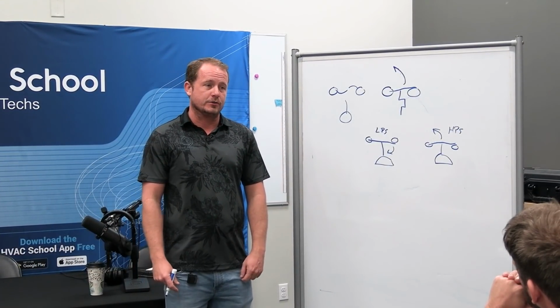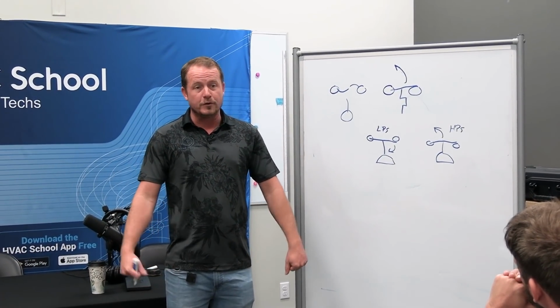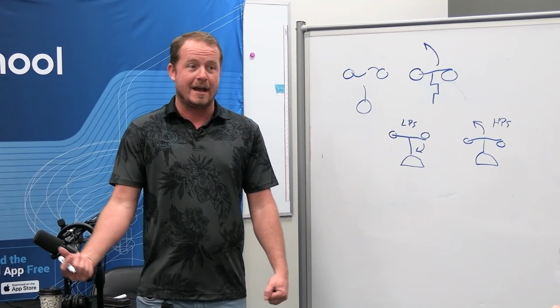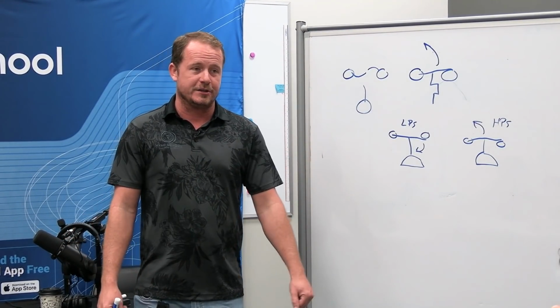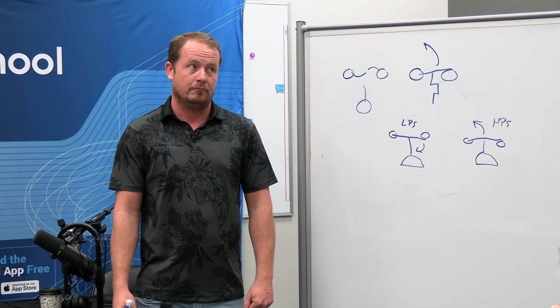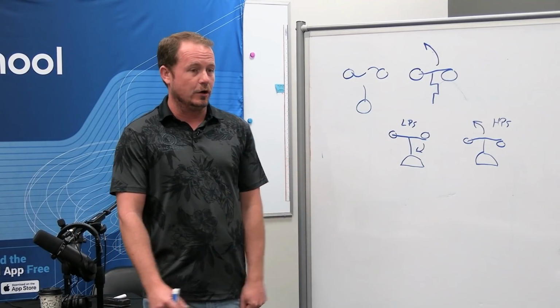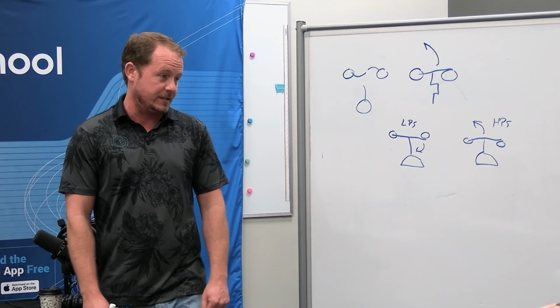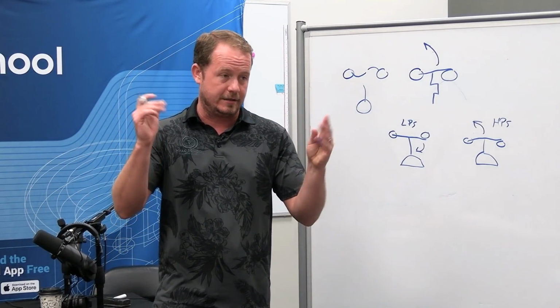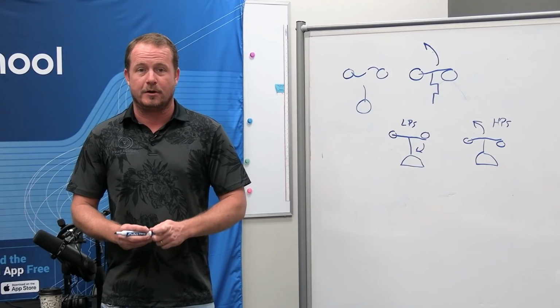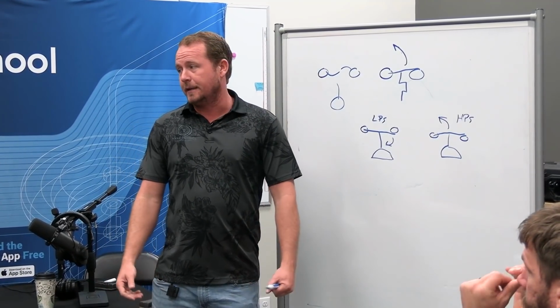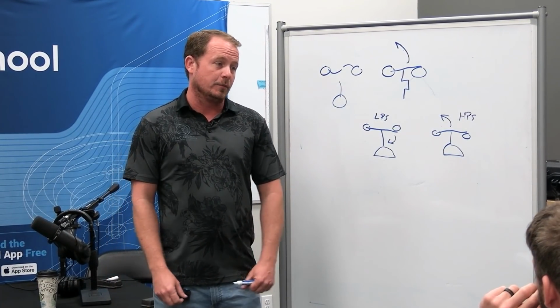So if you find a pressure switch that's stuck open, the first thing to figure out is whether it is currently in that condition. You have a low pressure switch that's open, what's the first thing you do? Check your low pressure, see if it's way too low, and then maybe that's why it's open. But say you check it and it's not way too low. System's off, pressures are equalized, and they're what you would expect as far as standing pressure. You would say, the low pressure switch is keeping the system off, so I have a failed low pressure switch.